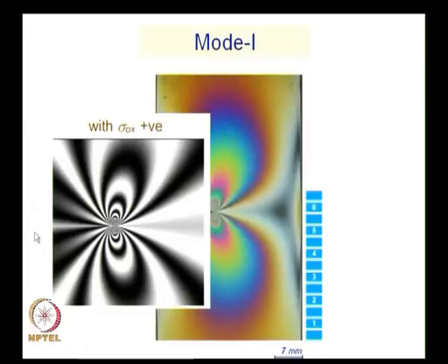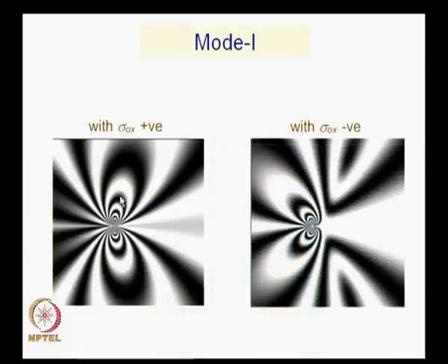The crack was long enough, it was close to one of the boundaries of it, and I also mentioned it is in a stress concentration field. So, in that case you got a frontal loop. People also have noticed when the crack length is longer in the case of SEN specimens, you have a frontal loop. And we also noticed earlier, by modifying sigma naught x, the sign positive or negative, the characteristic fringe patterns you see near the crack tip change totally.